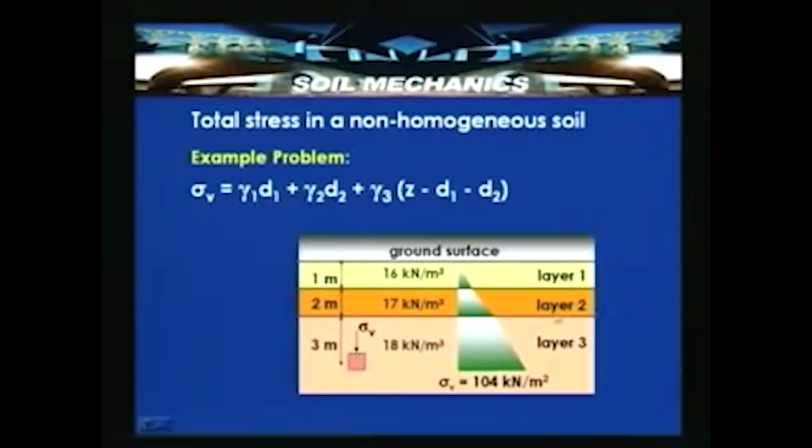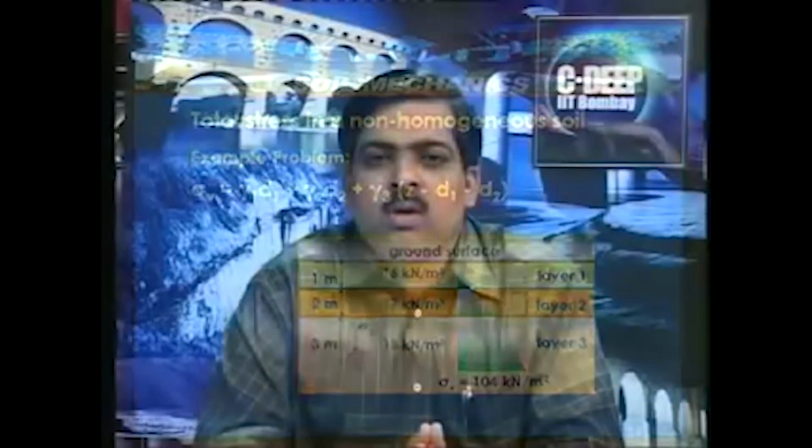So, in that case we can determine the resulting vertical stress can vary like this, and there is a chance of varying slopes because the unit weight is changing. So, there is a change in the variation or slope of this vertical stress with the depth variation.